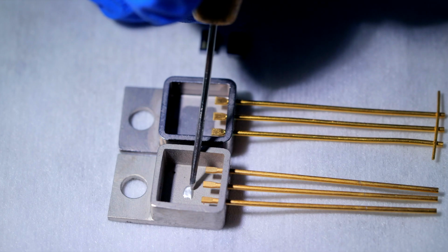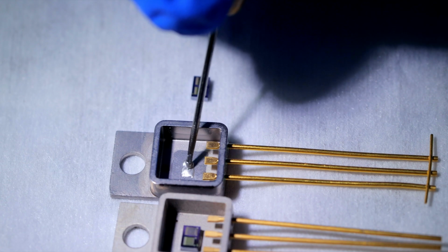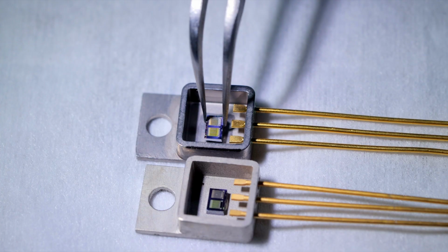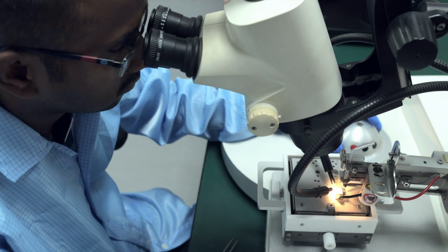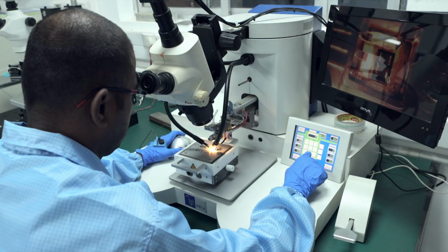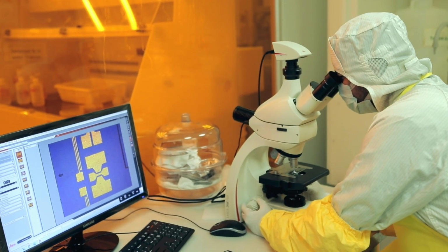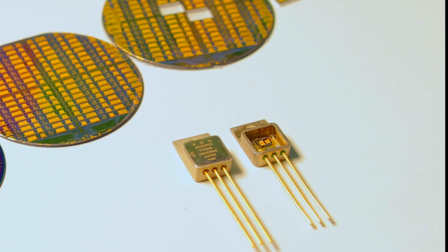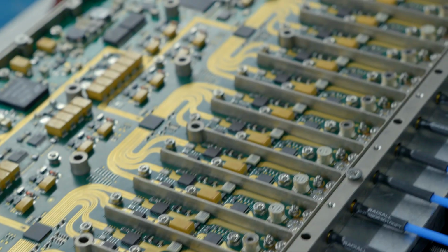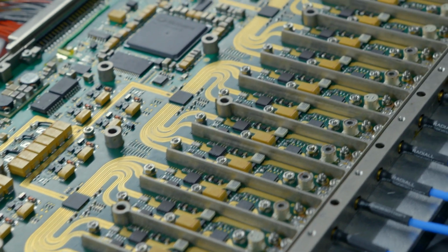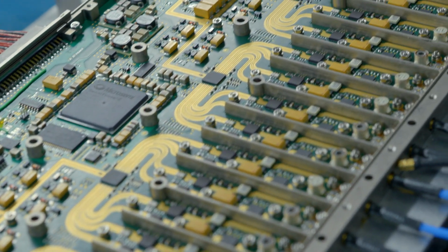After dicing, the dies are now first mounted onto a package, and then wires are bonded to the very small features so that the external world can make electrical connections with the circuits we have made. The package is now closed. These are the components you see on any PCB inside an electronic device. The life of the wafer now ends, and that of the device begins.